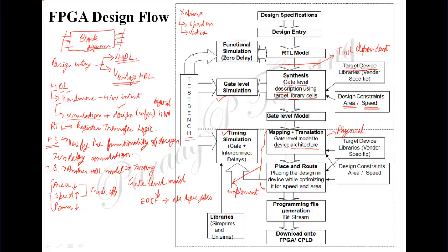And sometimes in the industry we'll also perform a simulation which is called timing simulation, which incorporates gate delays as well as interconnect delays, because now there are interconnects along with the gate delays, and therefore we'll perform timing simulation beyond that. And that's an optional case. This gate level simulation and timing simulation is optional when we go for academics. However, in the industry, it's pretty mandatory while doing product designing, right?